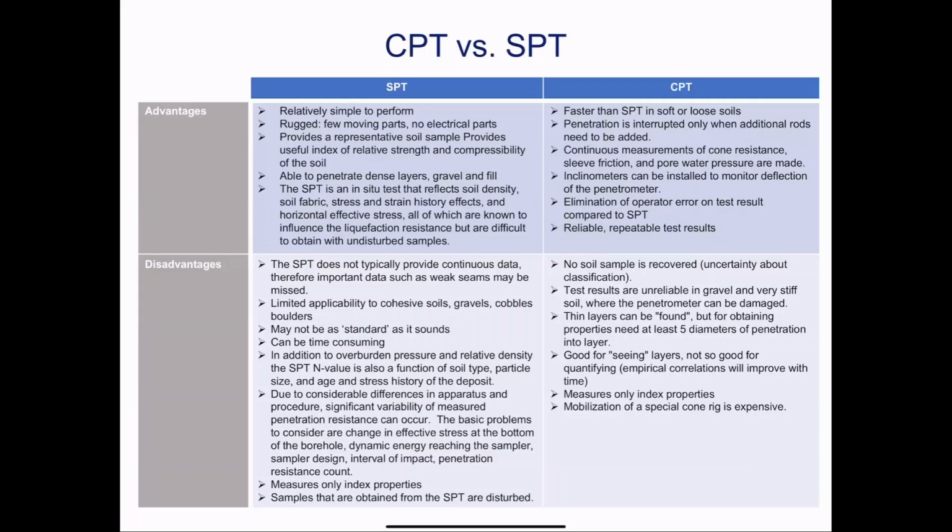And if the correction is not done properly, let's say each of us in this room do an SPT test with a different SPT device, there can be several orders of magnitude of difference in our obtained N values for the same site. And bullet point 3 says non-standard terminations. Yes, what's the termination criteria? If you just superficially look at the GI report for 2 sites and you look at the N values, you have to first ask yourself what device was used, how did they correct for N60, what was the termination criteria before you compare these N values.